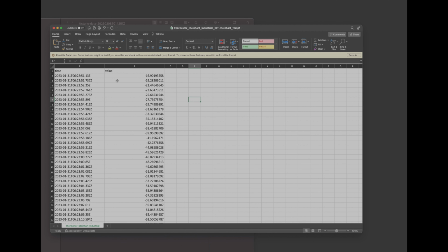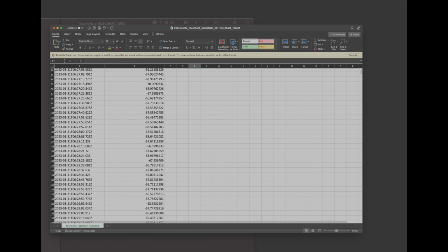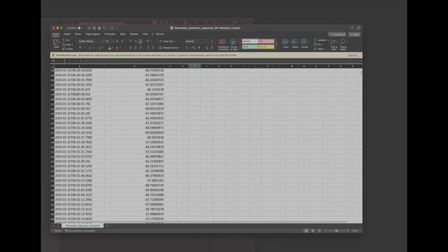And here we go. It's done our data logging for us. So we have a data log here now. I got it from our email to download, and it's in Excel now. And we have our date, time, temperatures. It'll even do data logging for you, all with the Arduino IoT Cloud.